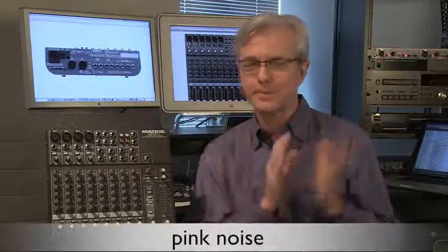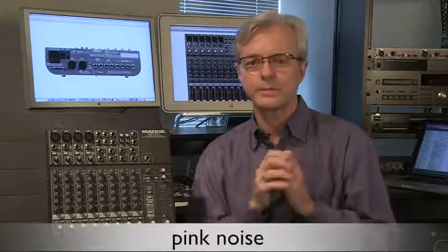So a sound engineer, when they come in to set up a sound system, they have to be checking the room to see where are the frequencies that get over amplified in that particular room. Every room is different. So they will take a spectrum analyzer, they will run what's called pink noise, and we'll be talking about that later, a pink noise generator which sends all frequencies into the sound system. And then they measure the output to see, are there places where certain frequencies are getting amplified because of the acoustics of the room.